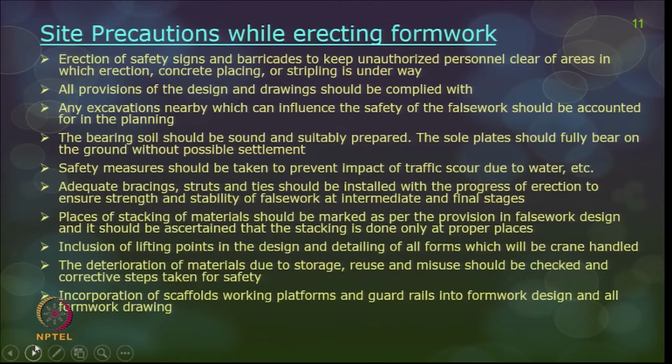There should be adequate places marked on the drawing itself where your materials and equipment can be stored, and only in those earmarked places should your material and equipment be stored when the concreting operation is going on, and no other places. You should be fully following the design criteria for that.